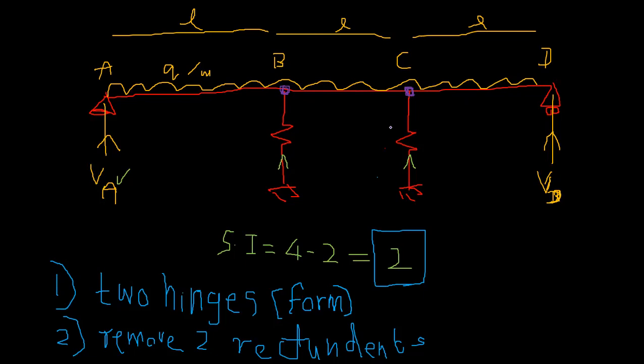So please remember, the stiffness is given in the axial direction, right? If you apply an axial force, your spring is like that. Think about just a spring, right? It is given the axial stiffness, but it has not been given how much it will bend. If you apply a bending, it will bend, right? That lateral stiffness or any other thing is not given. So we apply only an axial force in that spring, right?